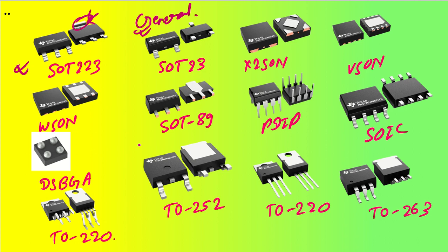3-pin package, or even 5-pin or 6-pin package. So this is very good, with input, output, and ground, as well as input, output, and some feedback resistors, and not connected pins that will be there. The XSON package is coming up these days because of very small applications like wearables or smartwatches.